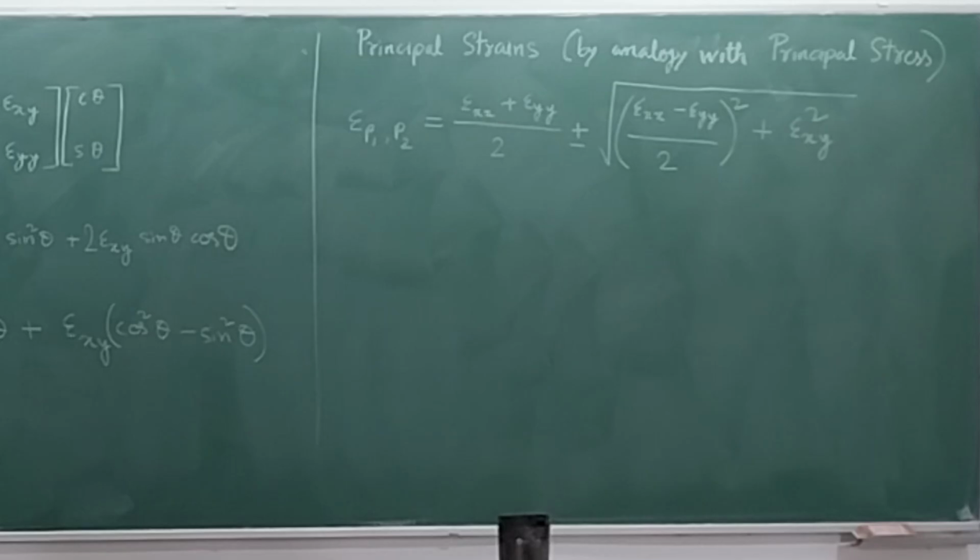It is basically an experimental device by which you can measure the strain in an indirect fashion. We make the connection with resistors. A strain gauge is basically like a resistor. Now you can have change in the dimension of the resistor, because you know the formula from class 11 and 12, that resistance is equal to rho into L divided by A. So when you attach a strain gauge to a body, and please note that you can attach a strain gauge only on the surface of a body, when the body deforms, the resistance will change.